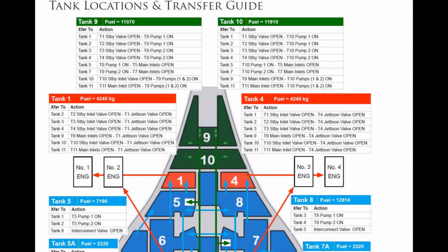And last but not least, before we get into setting up our actual flight, and I walk you through that whole part of the video, in the Concorde documentation, I believe it's in the fuel section, there is a chart which shows you what actions you have to take to move fuel from any one tank to any other tank. You have to have this chart available.